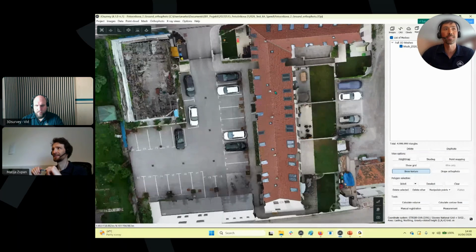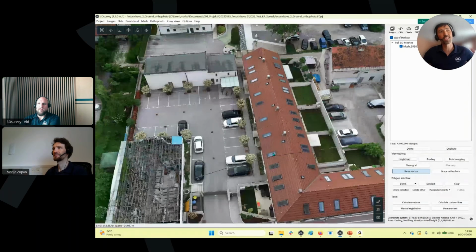How we actually came to this feature is right at the beginning when designing 3Dsurvey, we were producing a kind of traditional orthophoto where we were bringing buildings together. So actually damaging buildings, but getting out the building corners and what's actually on the terrain level. But now DJI drones are producing a lot of images with a lot of side images, so 3D oblique missions, everything like that, this is not possible anymore. But with the ground orthophoto, this is back and even much better than before, fully automatic.